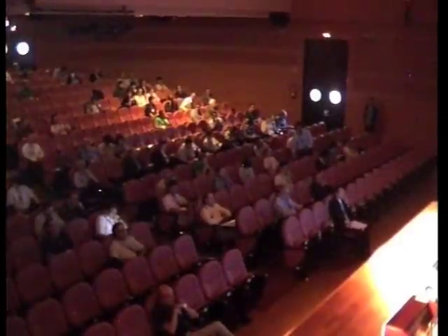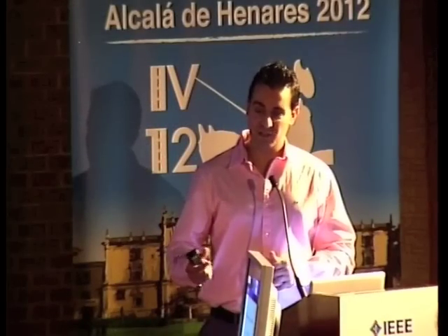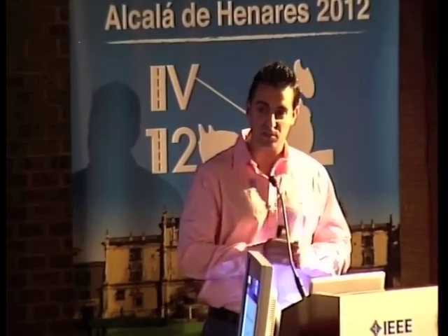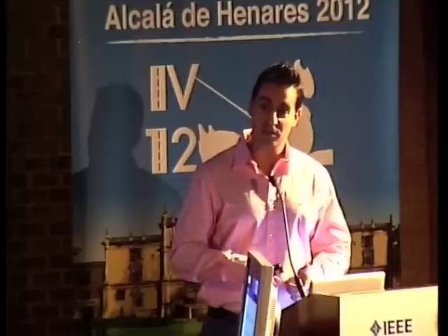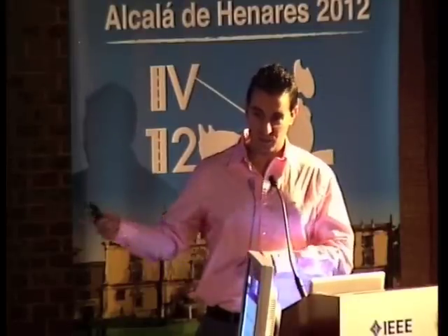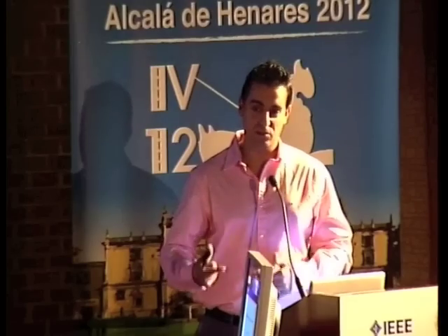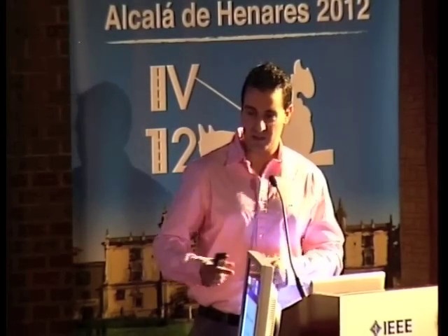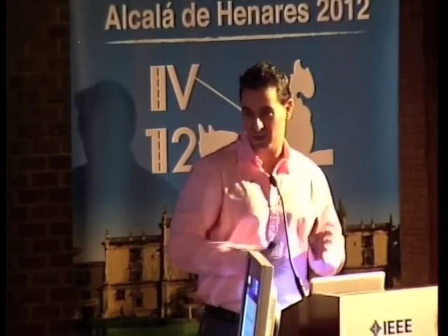This is done to characterize the noise. After that, when we design the filters, you will design the filter coefficients to be optimized in one direction. But when you design that filter, you need to know the covariance matrix of the noise. So this is done just to know the matrix of the noise. After that, you optimize the filter just focusing in one direction, the target direction.